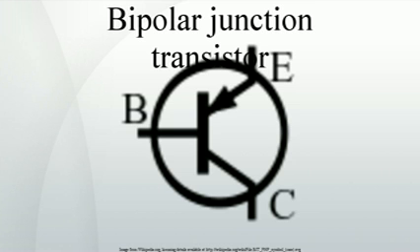Due to low-level injection, in which there are much fewer excess carriers than normal majority carriers, the ambipolar transport rates, in which the excess majority and minority carriers flow at the same rate, is in effect determined by the excess minority carriers. Detailed models of transistor action, such as the Gummel-Poon model, account for the distribution of this charge explicitly to explain transistor behavior more exactly. The charge control view easily handles phototransistors, where minority carriers in the base region are created by the absorption of photons, and handles the dynamics of turn-off, or recovery time, which depends on charge in the base region recombining.